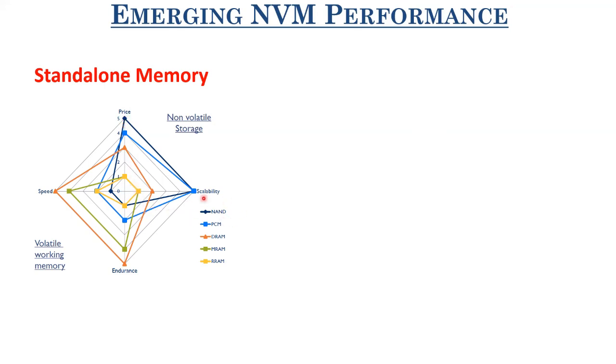So if you look at NAND flash, in terms of scalability, it's huge, especially with the advent of 3D NAND flash memory, where the NAND flash cells are stacked on top of each other. It's the densest of all the memories. And that is the reason why it's being used for SSD, cloud storage, and so on. So in terms of scalability, it's the highest. In terms of price per bit also, it's the lowest, and hence it's best with respect to price. That is why it has been rated 5. However, in terms of speed, it's pretty low, right? And in terms of its endurance also, it's pretty low. I told that it's only 10^5 cycles, right? If you operate it for more than 10^5 cycles, you're not sure whether you'll get reliable operation, or your memory characteristics will definitely degrade. So that is about NAND.